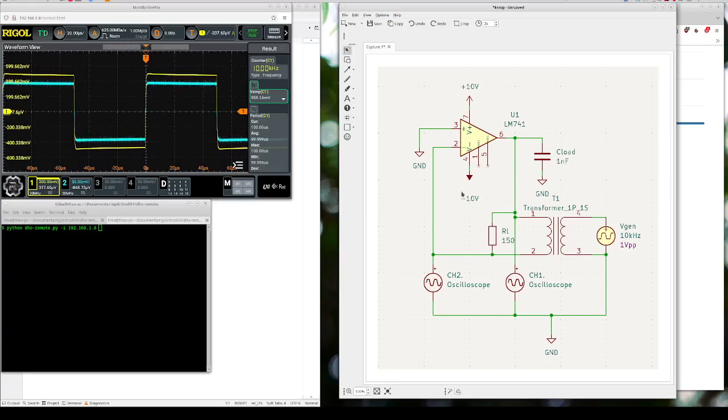DHO-REMOTE is a program I wrote to make a Bode plot with the digital oscilloscope. This time I want to show that you can also use this solution. It is an impulse-based transfer function determination. You can use that also with a linear control loop to see the open loop gain.